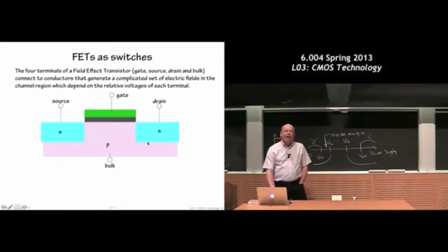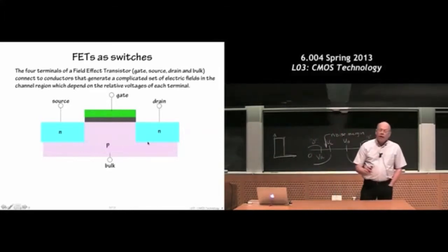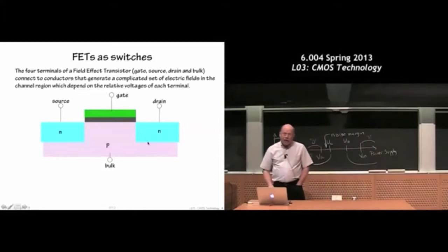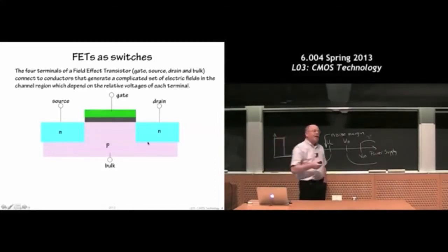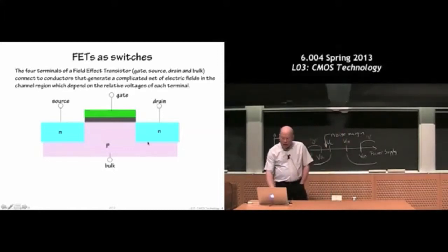The N-type devices are very much the same. It's a different sort of impurities that basically allow where the majority carrier is electrons. So p-type silicon has a majority carrier of holes. N-type has a majority carrier of electrons, and we basically just use different manufacturing techniques to embed these diffusions into the silicon wafer, and then we build a bunch of structures on top. A little layer of insulating oxide and this gate node.